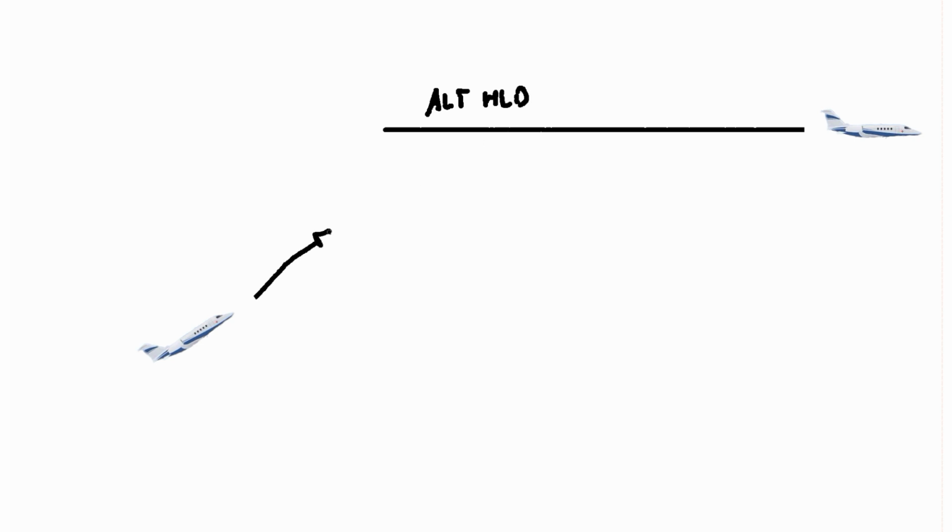So we can say that the function of maintaining the altitude, the straight line of flight, is this black line, which will be performed with the altitude hold function. Okay, this is the altitude hold. That's what altitude hold can do. But the question is, when I'm climbing, how do I bring the aircraft from this steady rate of climb onto this steady level flight? So this maneuver has to be done by a different function, and that is the altitude star or the altitude acquire function.